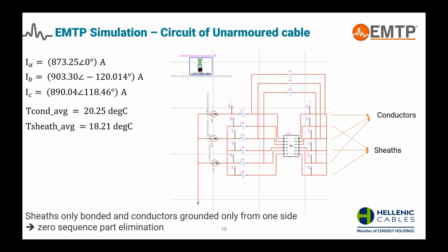We have the potential difference through these branch voltmeters at each of the phases, A, B, and C. A nominal PI device is used to represent the cable, and this is because we have a lumped model because of the short length, and we didn't want to go with wideband, for example, to avoid any fitting errors. Due to the fact that the inductive mechanism is the dominant one in our case, we can use it with ease in this validation.